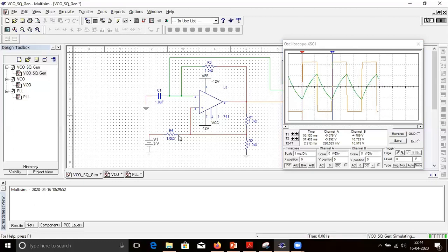So I have added external voltage, and which is 3 volts. So when UTP appears here, this voltage is also positive and UTP is also positive. So effect will be definitely there is a rise in non-inverting level. So instead of 5 volts, you will get more level for the UTP slightly, and for LTP it will reduce because this is positive and LTP is negative. So let us simulate again and see the change.